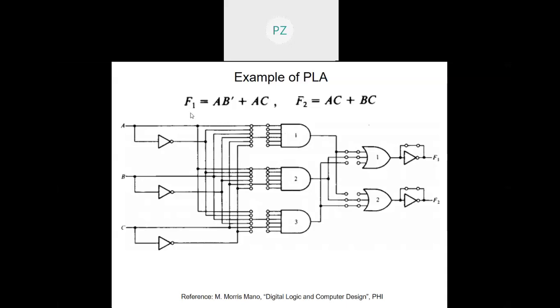So I should check whether F1 F2 is going to give me fewer product terms, or F1 F2', or F1' F2, or F1' F2', because that is going to save me in the AND array. So let us take that example.